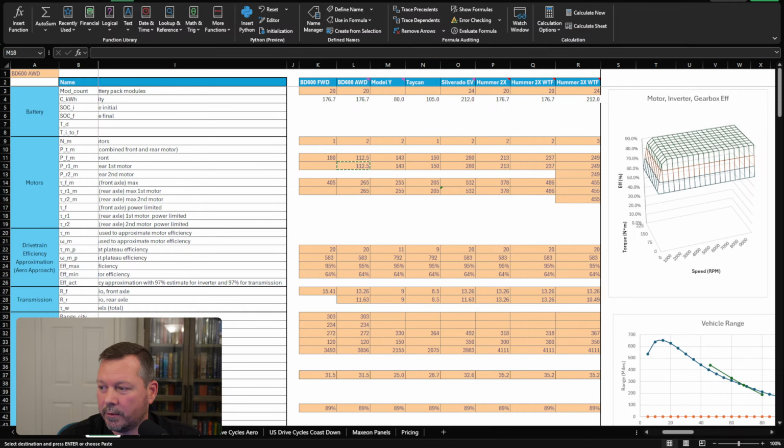Obviously a bunch of rivet nuts and drilling and stuff on the structure, and it's got a pretty strong bulkhead in the rear. It's mostly stamped, but it's still pretty rigid. And then in the front, it's got an extruded aluminum bulkhead that's really stout. So if you tie into that, you're good. And then internally, it's got these rails, extruded aluminum, that are pretty stout, but not as strong. So the bolts are exposed. So ideally, you tie into those, and then your main support, if you had anything heavy, will go to the front and the rear bulkhead.